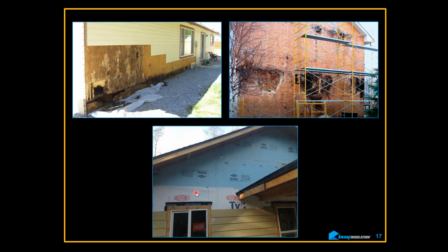And then this goes on top, the blue board goes on top of that, and this little capillary break behind it allows moisture that comes from the inside of the house to drain down or convect up and get rid of it, because the Tyvek is like, what, 23, 30 perms, somewhere in that neighborhood, depending on which one you buy. And this is like class 1. It's, you know, less than 0.1.